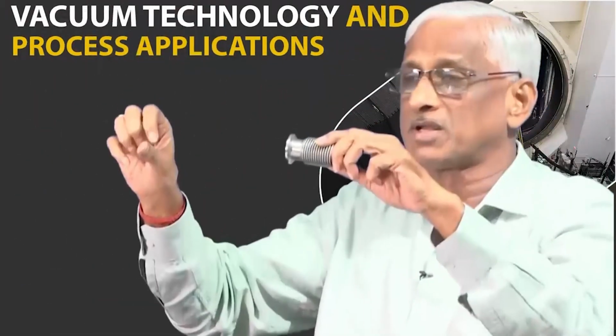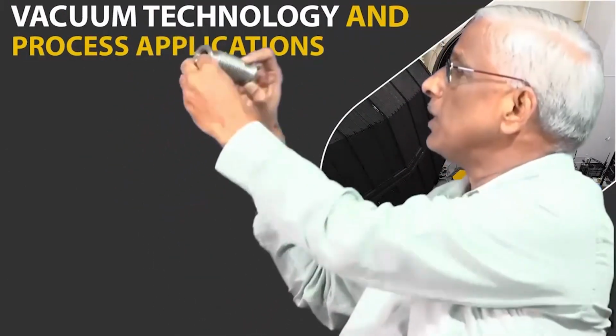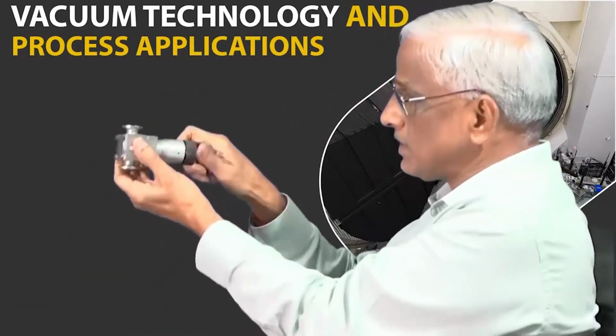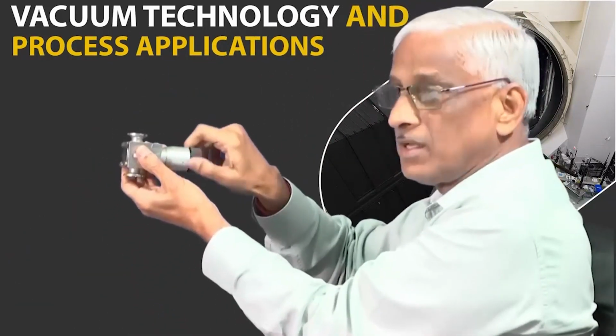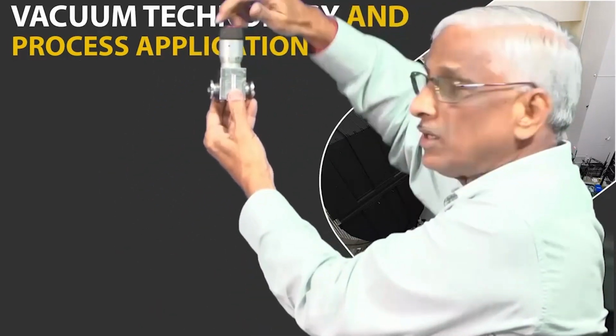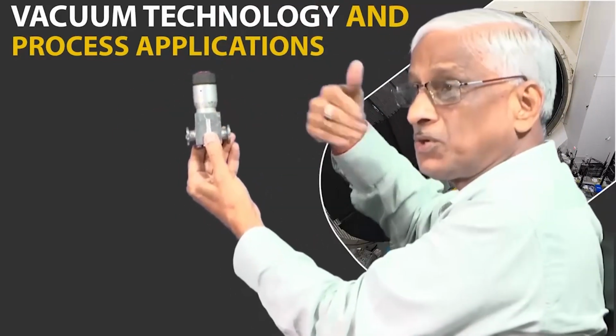And if you want to have flexibility in a long piping network, because it is not matching, then you require a flexible bellow. This is a flexible bellow. And valves are there. For gas inlets, there is a calibrated flow rate needle valve, through which one side is atmosphere, the other side is connected to high vacuum.